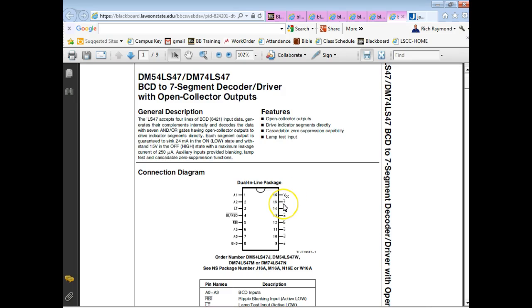They've got bars above them. What does a bar mean? That means they're low active. So this guy drives a common anode display. What we would do, I can't do it on here, guys, but we would put a resistor in each one of these lines. We either use resistors, or normally we use resistor packs.